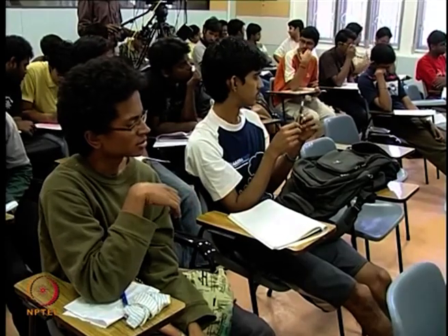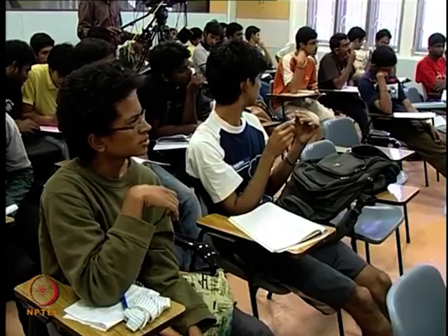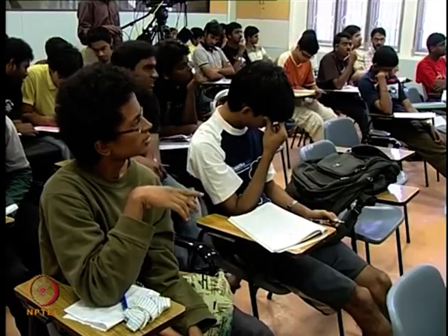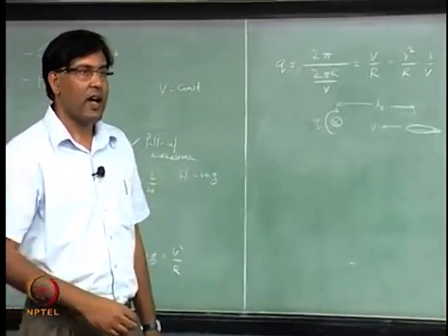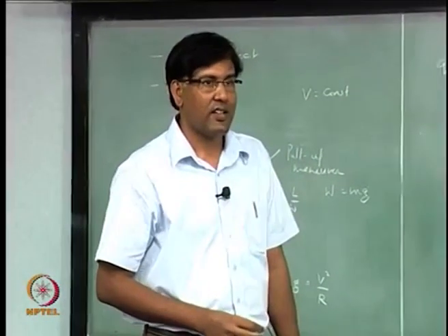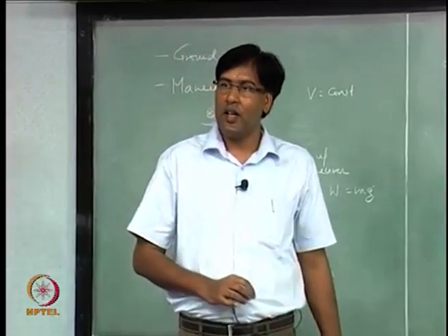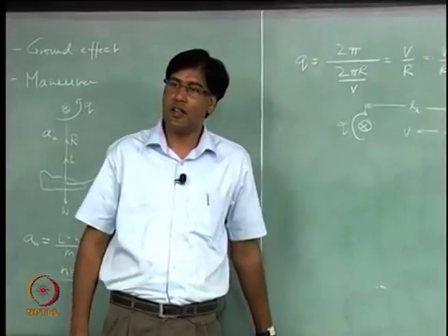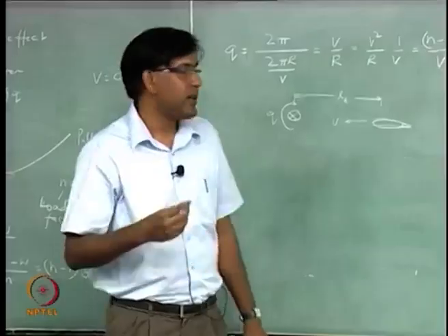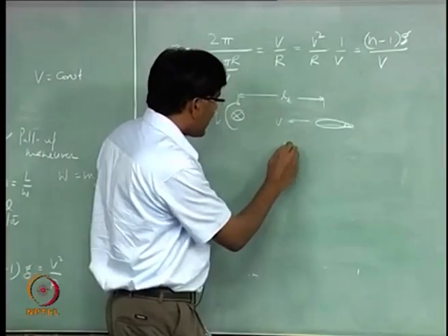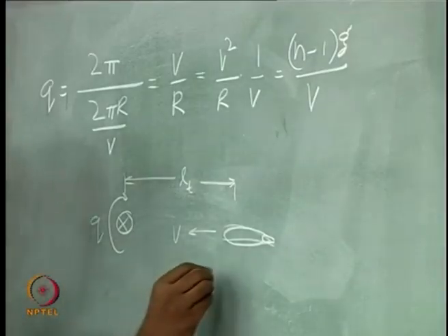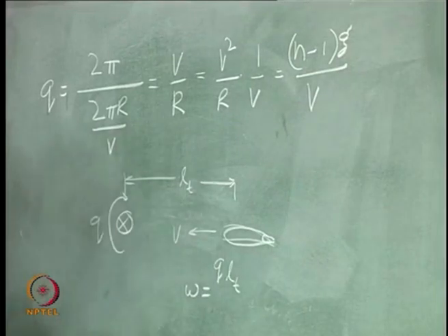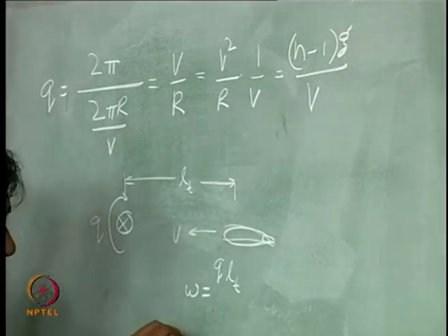Okay, I deflected the elevator. Afterwards, I see a pitch rate, and because of that pitch rate, this tail starts pushing air down. So you see a relative air upward, and because of that, the angle of attack at the tail is changed, right? The vertical component of velocity will change, which was not there before. So what is that velocity? Let's say I call this W, which is Q times LT, right. So delta alpha is going to be